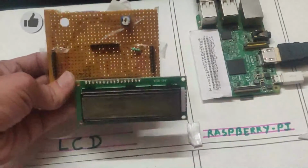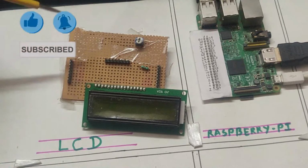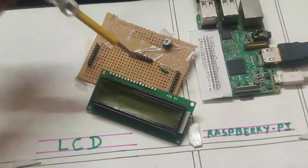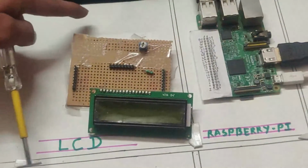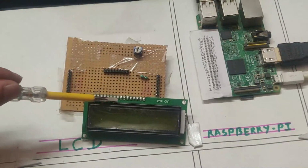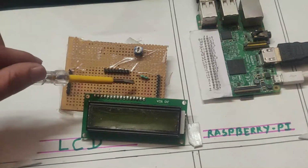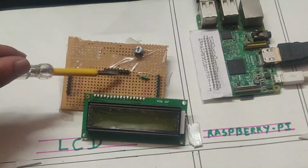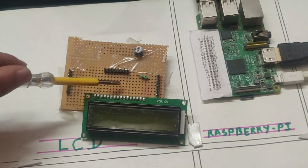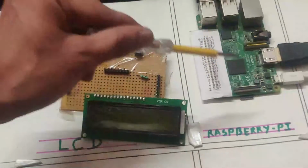Okay, now with this you can see at this side we have common VCC, at this side we have common ground. Then at this point you can see there are the input pins of this LCD module. The first pin is the RS pin, then enable, then D7, D6, D5 and D4. So these are the output pins of this LCD. We will connect only these pins with the Raspberry Pi, and the VCC and ground pins also with the Raspberry Pi.